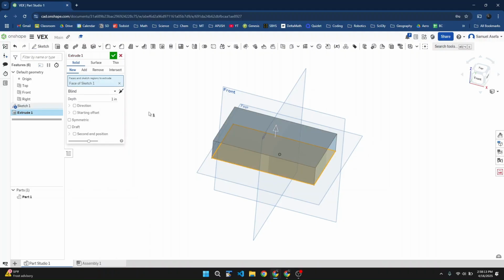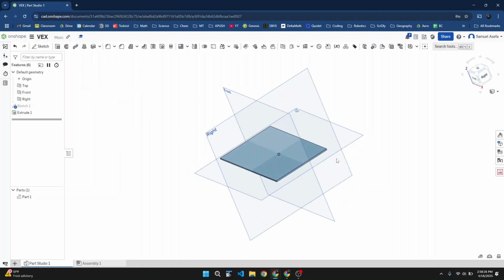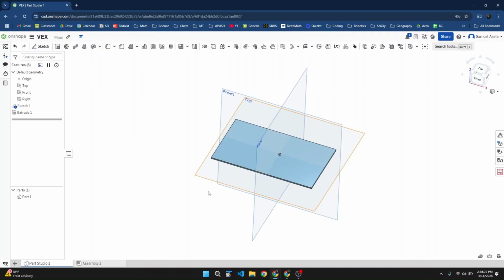So once you have your 2D design, you just make it 3D and click extrude on your face. So once you have a face highlighted, you would just give it an amount to be extruded. So for example, for Lexan, it would just be 1/16th. And this is a basic way of creating Lexan, which we'll cover more later on.